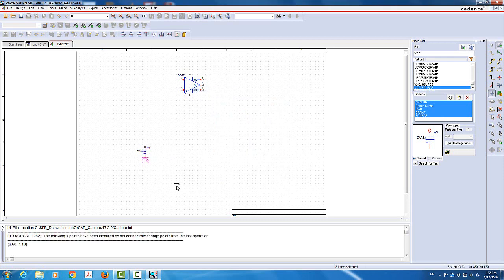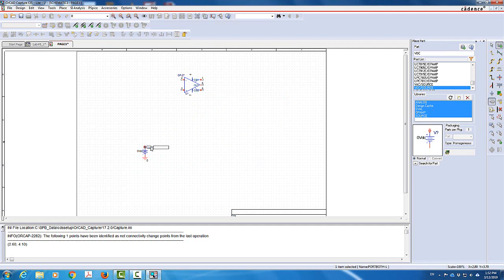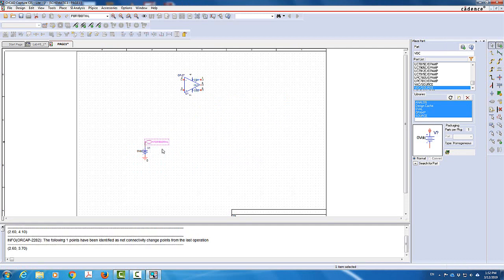And then instead of connecting this voltage source directly, I will use the port. So I will place port. I will do it for both, which means input and output. So I will use it as a port. It will make it simpler to draw the circuit. Now this port in ORCAD, in the professional ORCAD, if you want to do the PCB design for your circuit, says that this is an input output port, but here I'm using it as a node.